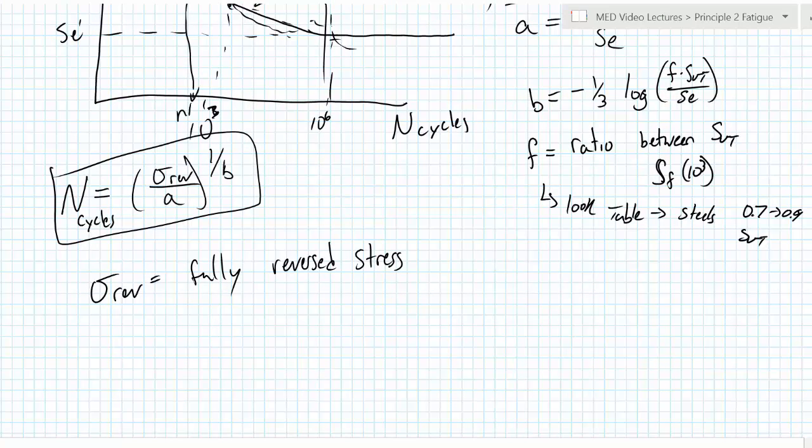And when we do this, you're going to come up with some number that looks like it's going to last 106,582.134 cycles, right? So if you take the log number of this B and raise it to the fractional decimal power like that, you'll get that many cycles.